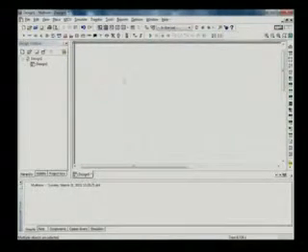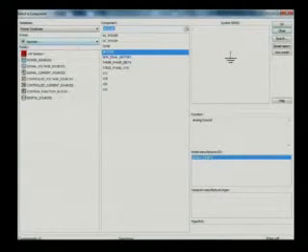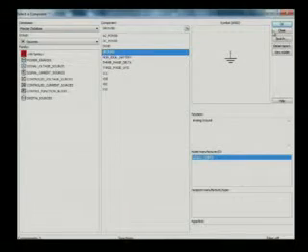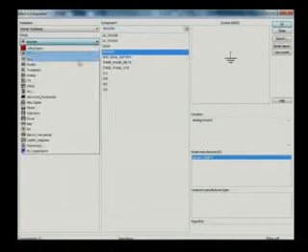We will right click on the workspace, we will have place component, we will take one DC power, that's DC volts. Then we will have one ground source, then two resistances that I am taking.